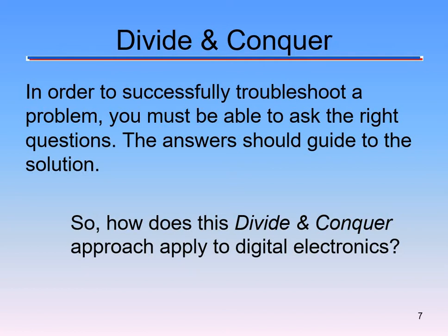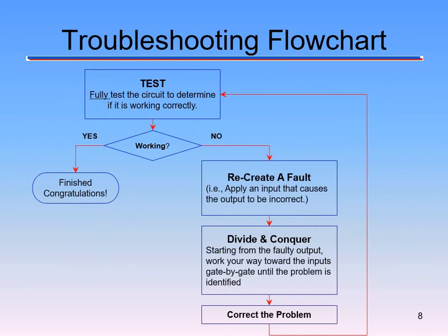That's why I say, when you're breadboarding, most important thing is, when you put your ICs in, do all the power and ground first. Don't come back to it. Have a method to what you do. So when you troubleshoot, it makes it easier. Also, when I've talked about breadboarding, don't make big loops with your wire. It's harder for me to come over and help you, and it's harder for you to troubleshoot later on. So these are things that we can divide and conquer on early. Always power and ground your chips, and make sure that you have your wires laying as flat as possible, so it's easier for us to come over and analyze what's going on.